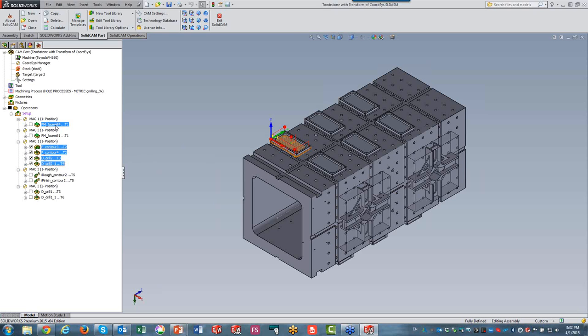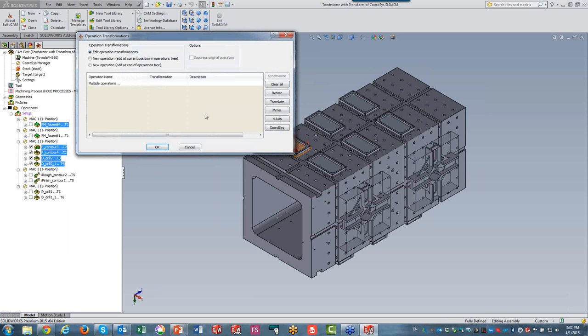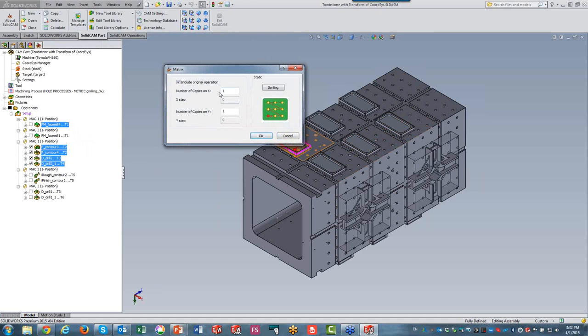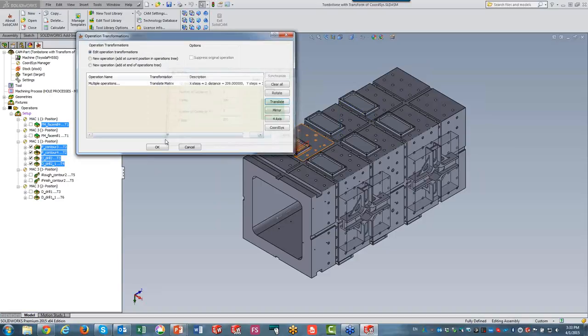Now let's start my transform. If I go to transform, note what we have here. I can say, all right, let's just put it on different coordinate systems. But before that, I can also show you that we can combine different types of transformations together. For example, this side, I decided to do it via translate. So I'll click on translate, matrix, the exact same way I did it before, with the right values for my distances, and that's all done.